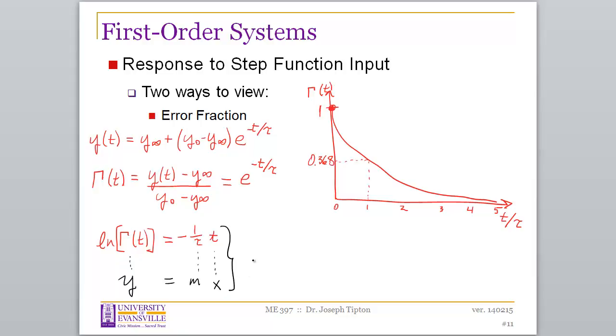So you could actually test a measurement system to a step function input and then graph it to calibrate. And by calibrating, I mean you can figure out what the time constant is of the measurement system. Once you know the time constant, then you realize it's going to take 4 or 5 time constants in time before the system is able to accurately measure an input signal.